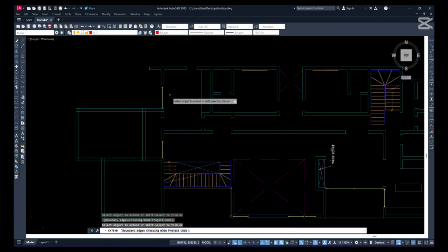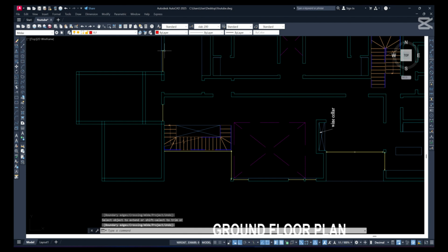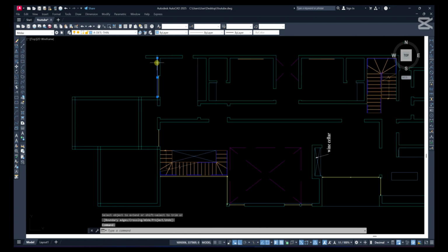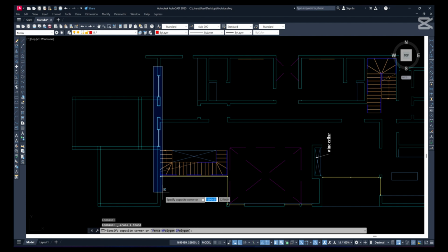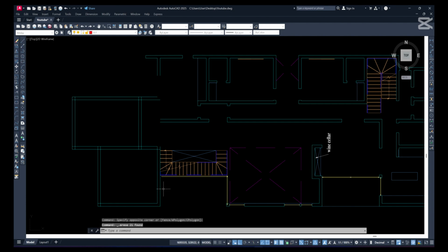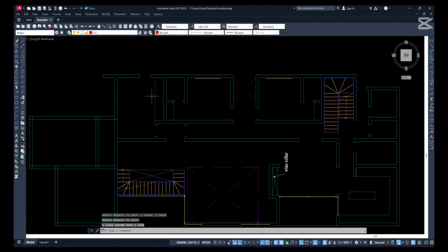So we use the walls, the partition walls the architect provided, as a guide to introduce our beams, meaning that our beams have to flush within the walls. Likewise, our columns, they have to hide within the walls. So the architectural walls are there to guide us.